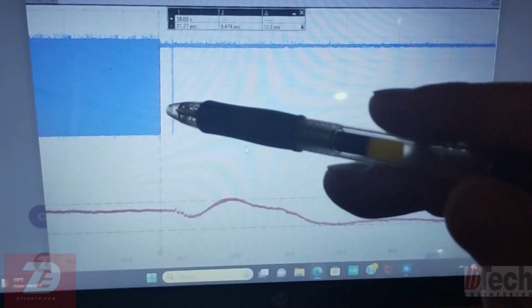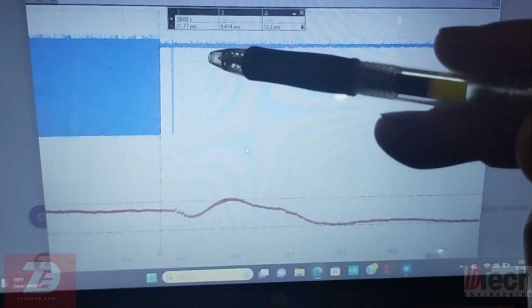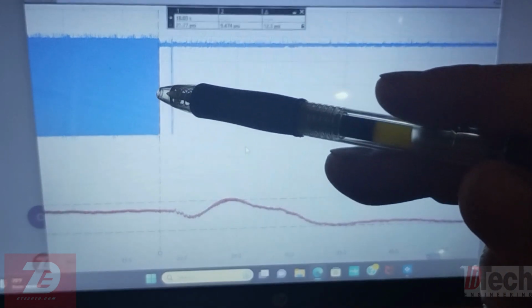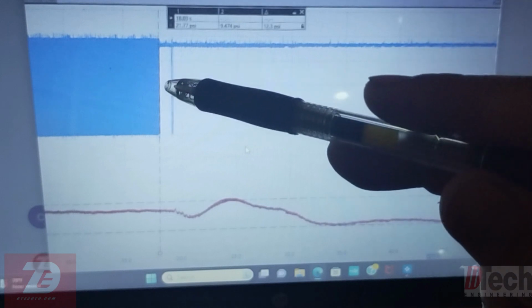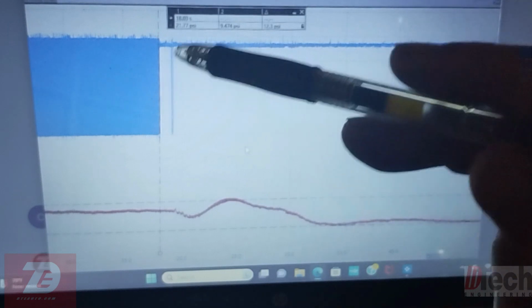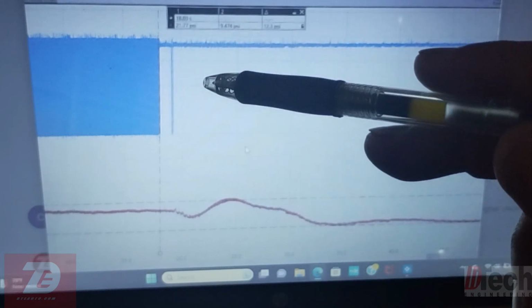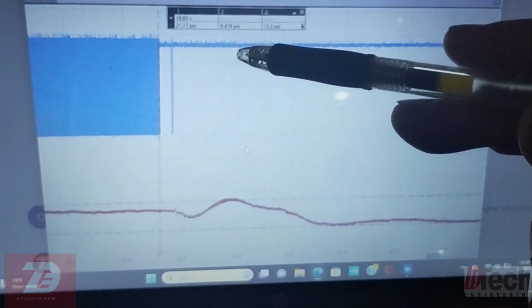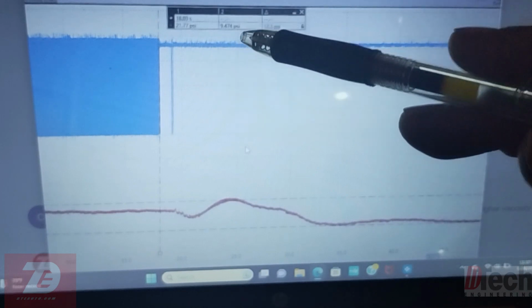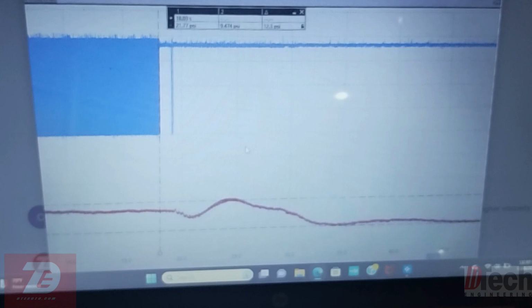Obviously, we lose control of the oil control valve at this point, and you can think that the DME just goes into faulted state or stops being able to control it and make a wrong call and say that the DME is being the cause of this low oil pressure issue because it stops being able to control the valve.